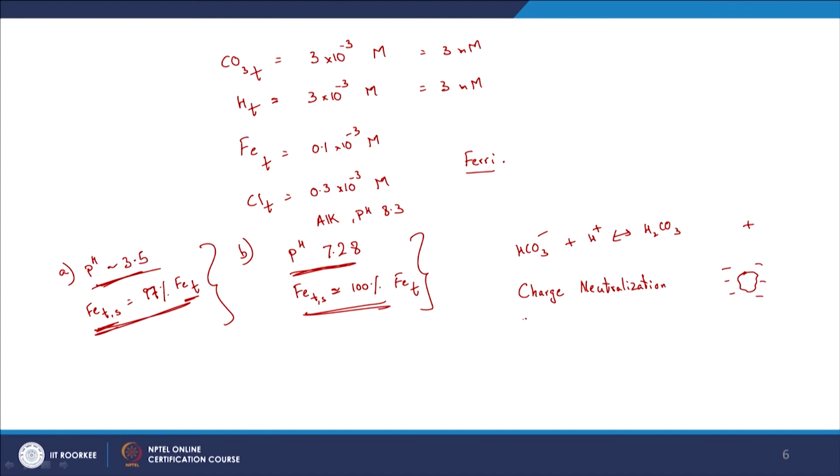And the second aspect is sweep flocculation, as in now you have this Fe(OH)3 solid that precipitates out, which is what you saw here. So these particles are either going to aggregate on the existing suspended particles and create a bigger particle, allowing it to settle down, or they themselves act as adsorbents, or sites for the other particles to be entrapped on them.